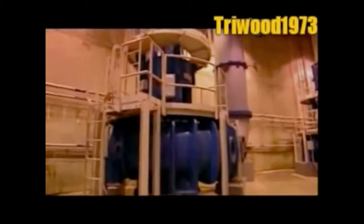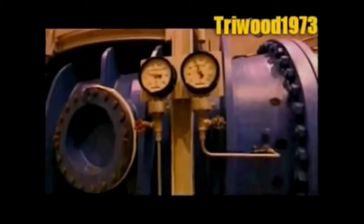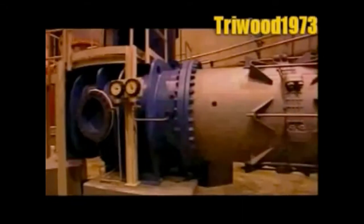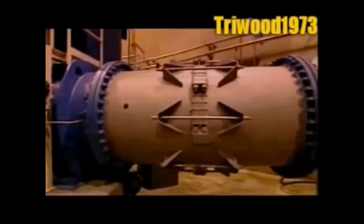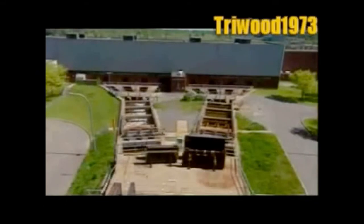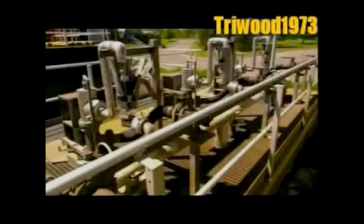The water flows from the wells to giant pumps that force it to the surface. The plant has backup generators to keep the pumps working in case of a blackout, and devices to prevent water from backing up should a pump have to be shut down for servicing. Once the wastewater reaches the surface, it flows through the pumping station down discharge channels leading to the treatment building.